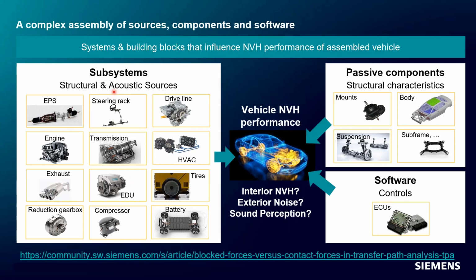And the force going in will depend on the connection between the engine and the subframe. What these blocked forces are, those are the forces generated by the engine independent of the connection it is associated with. So it's a characteristic of the source strength. There can be different sources, structural sources or acoustic sources, like the electric drive unit, the transmission, electric power steering.